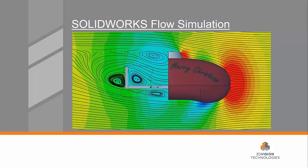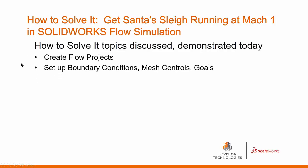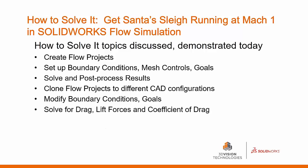So there are just a number of things to cover with getting Santa's sleigh running at Mach 1 using SOLIDWORKS Flow Simulation. The topics that we discussed today were creating flow projects, setting up boundary conditions, mesh controls, and even goals. And then we went through solving and post-processing the results. We also did cloning flow projects to different CAD configurations, and modifying boundary conditions and goals to match. And ultimately, we solved for drag forces, lift forces, and coefficient of drag as Santa's sleigh is flying at Mach 1.